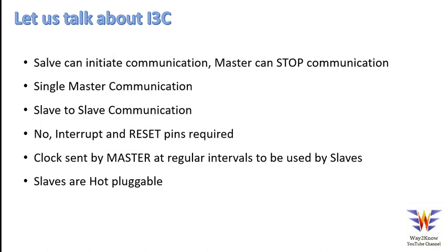As we said previously, if the slave wants to talk, there are additional pins required like interrupt and reset for I2C, but here the same requirement would be done using the data and clock pins itself without the need for interrupt and reset. So one major thing here is that for the slave to perform some of its internal activities, the master would be sending a clock signal at regular intervals, just randomly, so that the slave can perform any internal operations that are required.